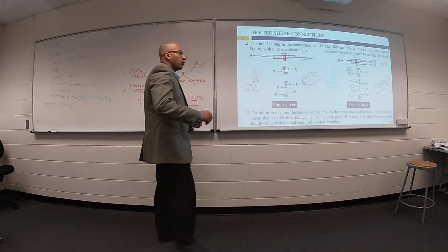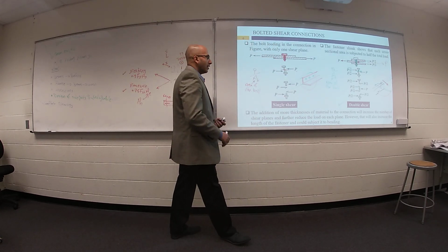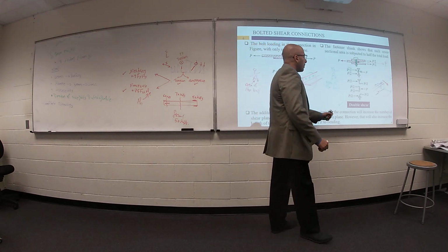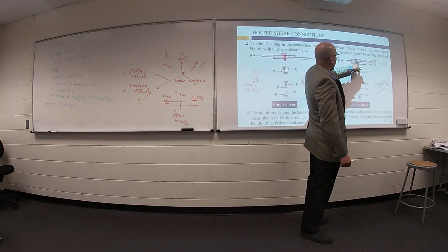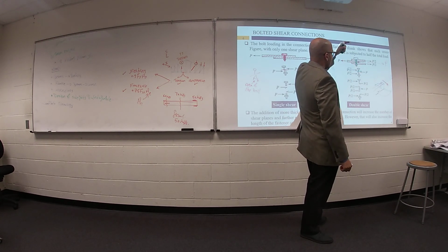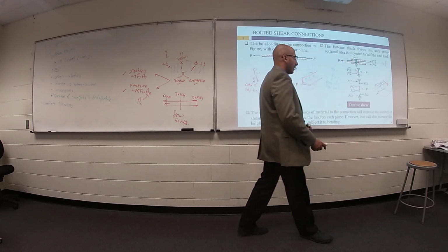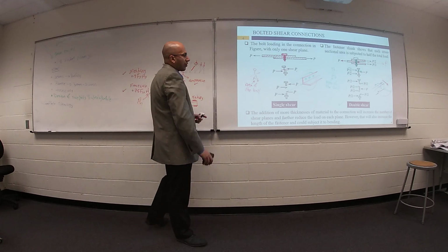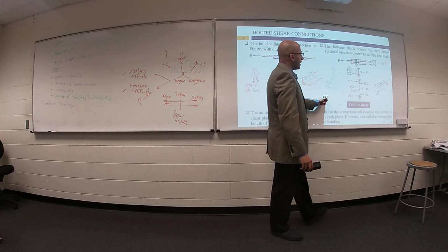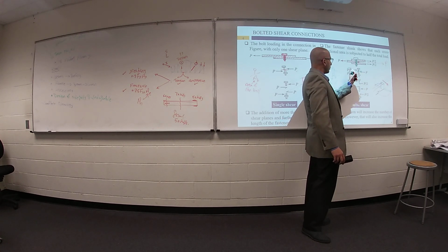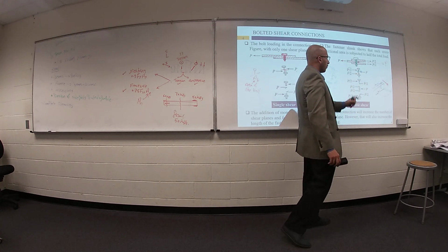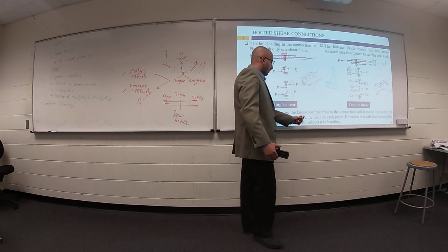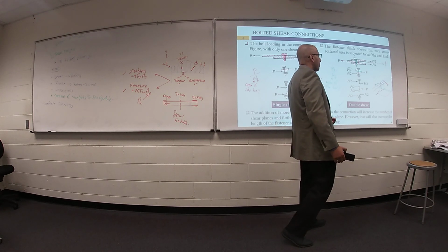Anyway, we have something called single shear. We have only one plane in the bolt under shear off. Double shear, we have two planes in the bolt under shear off. We added more thickness of the connected material. We like the double shear case more than single shear because in this case the planes of the bolt will be under a smaller value of load. However, increasing the length of your bolt makes it subject to bending.